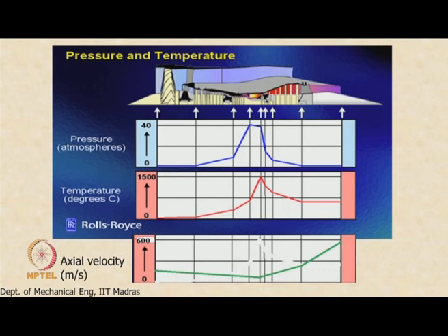But when I look at the axial velocity alone, this is about maybe 150 meters per second, and it is going down here, so the temperature is increasing, so the Mach number is actually decreasing. It may be high here, where the speed of sound may be 300 meters per second or 330, so the Mach number can be 0.5 here, but as the speed more or less keeps going down slightly, the temperature keeps going up, the speed of sound increases and the Mach number goes down. So it tells me that maybe in this compressor, compressibility effect may not be large. That is what this one is trying to tell me.